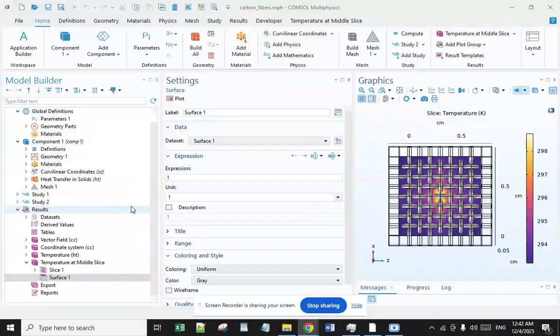As heat transfer is dominant through the laminate's thickness, the thermal conductivity in the direction transverse to the fibers is critical. It can be predicted by the harmonic mean, also known as the inverse rule of mixtures, but that indicates the lower bound on the composite conductivity.